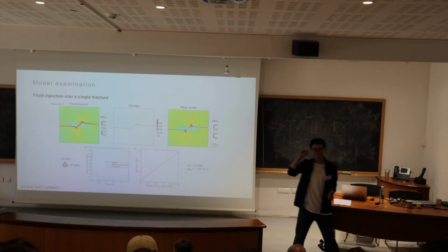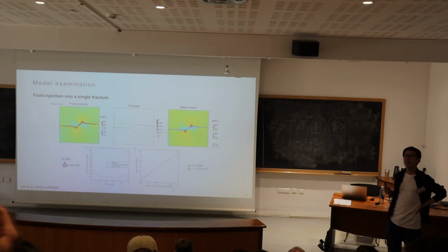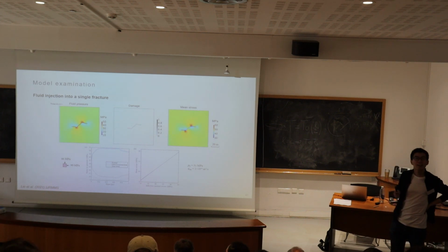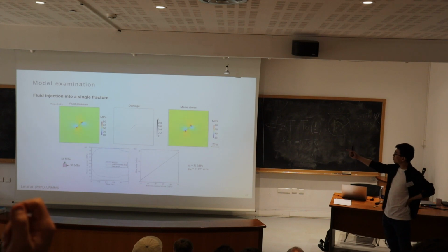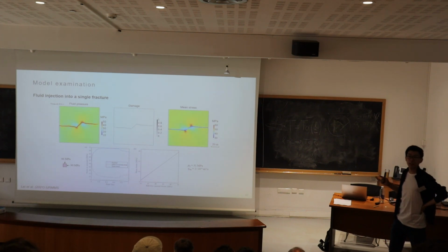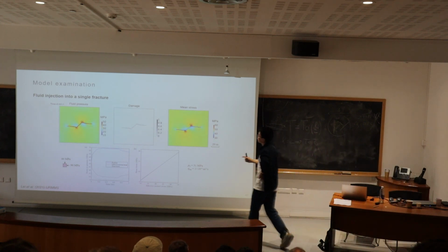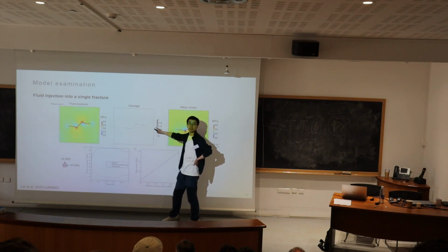Sorry, I still didn't get the question. There should be, because there's damage. The point is that you recover the elastic part of the deformation, but you don't recover the plastic part. But I use the damage mechanics model, so it's an elasto-brittle model. So when the stress exceeds the failure criteria, it will propagate new cracks.